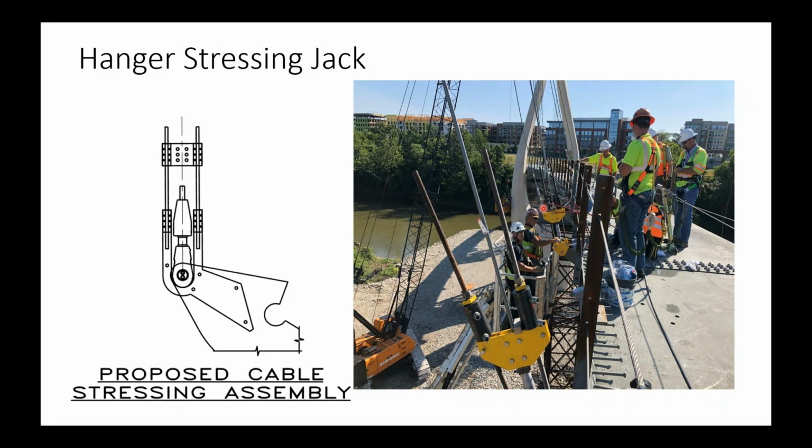It essentially involves a couple of bottle jacks connected across the turnbuckle. So the idea is you stress this, you pull the cable closer to the pin and take all the load off this turnbuckle, and you twist this turnbuckle until you have the design length set at the gap in this turnbuckle, and then you read off the force in those cables and those bottle jacks, and determine if you're at the correct desired design force at that stage of construction. And it worked very well.